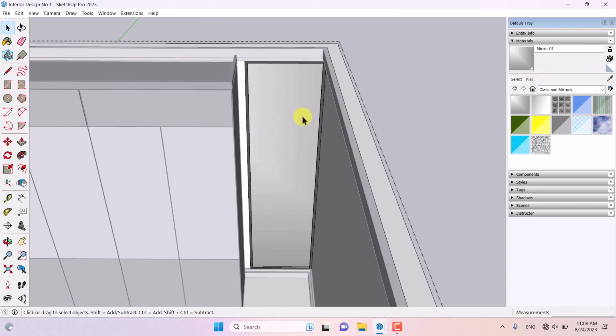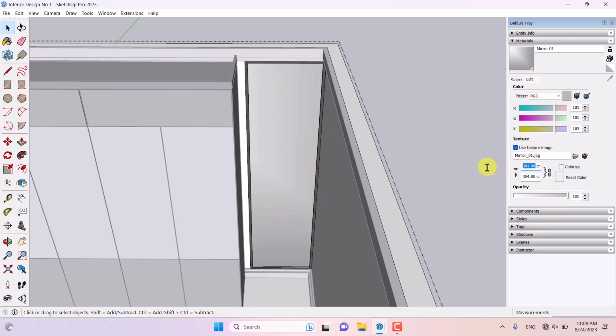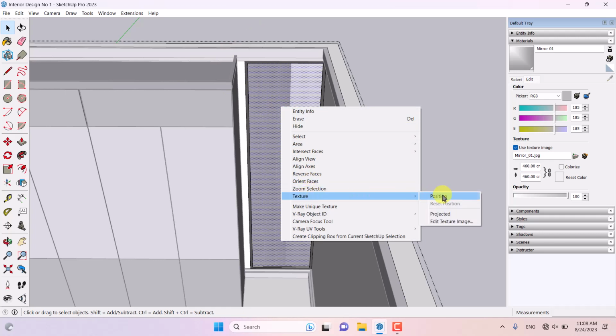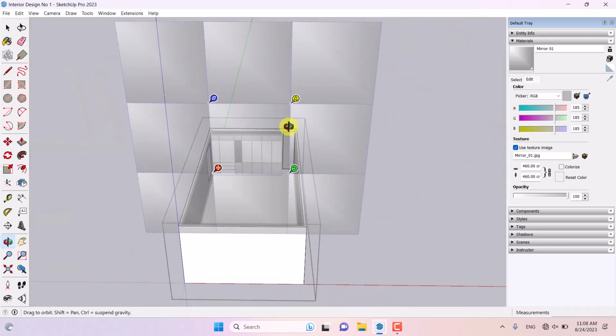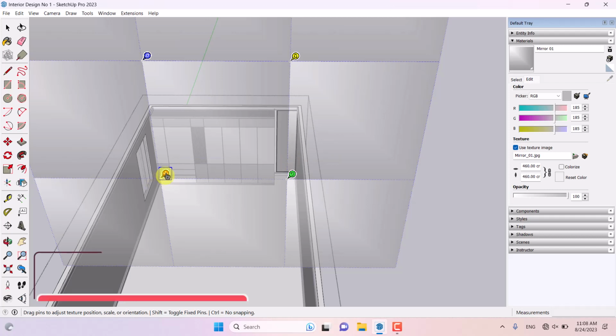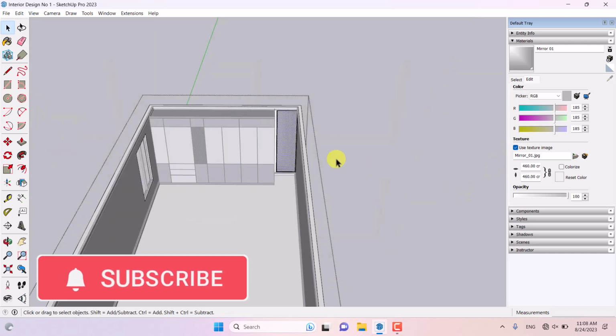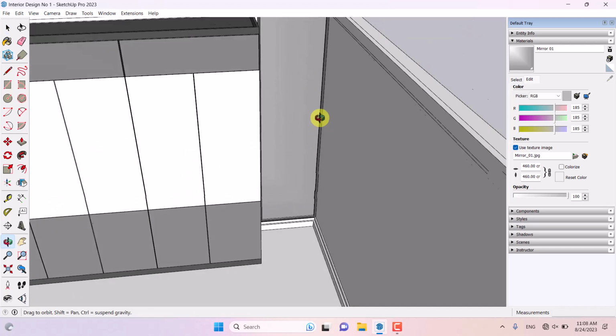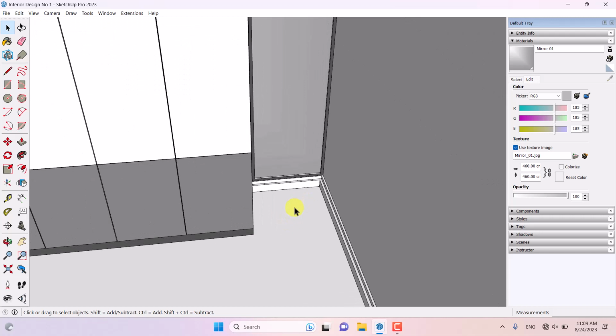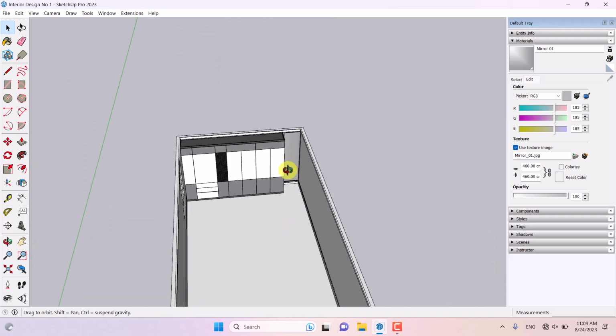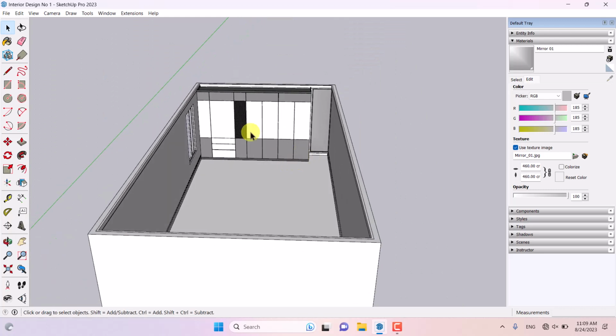So for fixing these problems in your renderings, you can click on the edit option and increase the value of the texture size about 460 centimeter like that. And click on this face, right click, and we have texture option and click on the position. As you can see, you can change your position very simple and easy with these red icon in here. Something like that can be really useful and wonderful. So we add the mirror in here, and you can add some type of vase or flower in this place to make your renders much realistic, but I will talk about it at the next sessions.